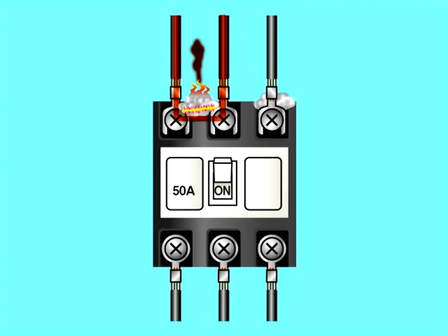To prevent such an incident, compressed air should be used periodically to blow away any dust that accumulates inside the control panel and switchboard. Use of cotton rags should be avoided because the oil on the rags could stick to the terminal board, making it even easier for dust to accumulate.